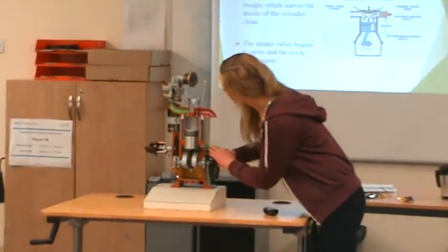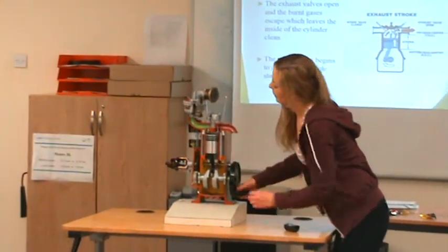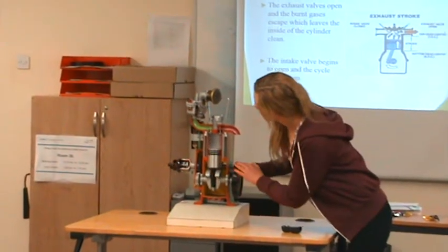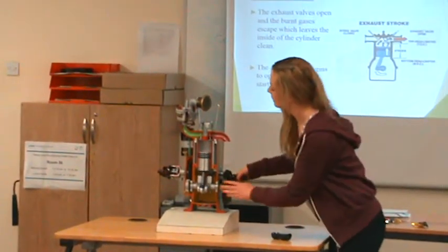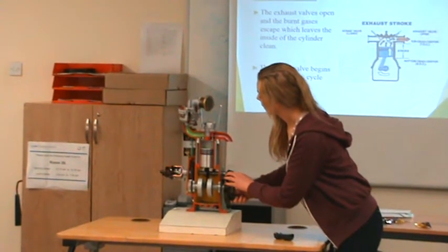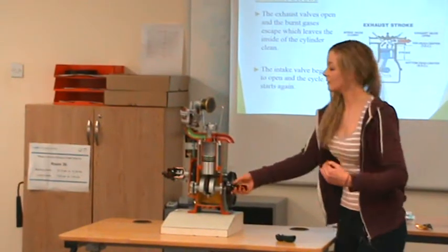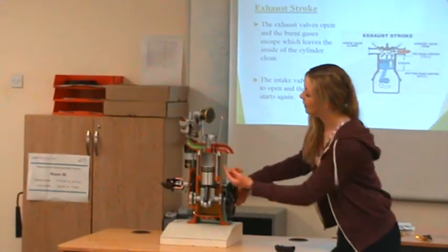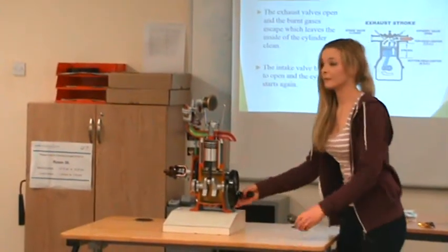And so if you look at this now, the 4 strokes. This is our intake stroke. You have your inlet valve open, your exhaust valve is closed. That's going to be your compression. Both valves are closed, the piston is travelling upwards. That's going to be your power, because both valves are closed again, and the piston is travelling downwards, so that's going to turn your crankshaft. And when the piston is going up again, that's going to be your exhaust stroke, so your exhaust valve is open, and your intake valve is closed. Is that okay? Yes.